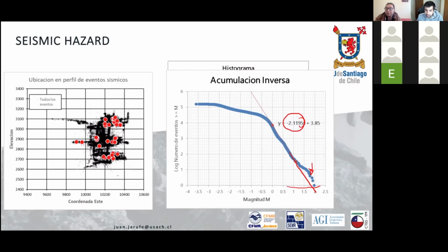Okay, thank you. I think it depends, as I mentioned in some slide, on the source mechanism. Sometimes your mine has different source mechanisms, meaning in some part of the mine seismicity is caused by high stresses, in another part it is caused by fault slipping, and in other parts it is a mixed behavior. In those cases it will be better to separate things and use one code to represent one thing and another code to represent the other mechanism.